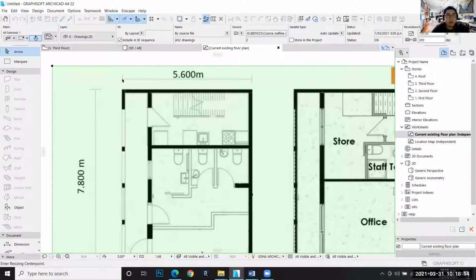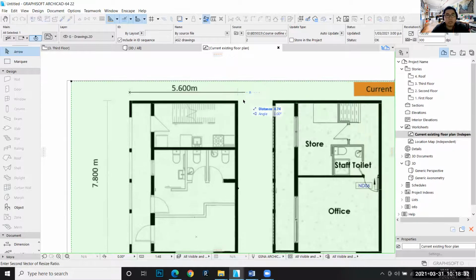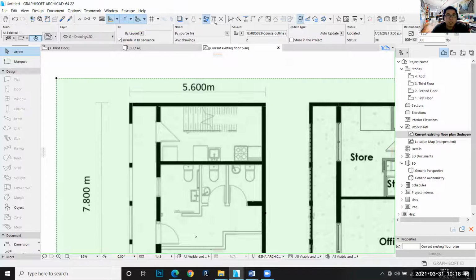So I'm going to use that dimension here. I click the first point, holding the shift key to get the line straight. Click on the second point, the second end, and now you see the image get bigger or smaller. I now simply type in the actual dimension, and you see the dimension of the line changing. So I type in 4556 and hit enter. I can check again using the measure tool, and you see it's close to correct.